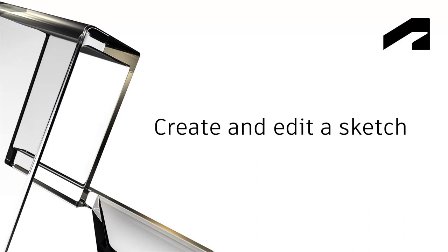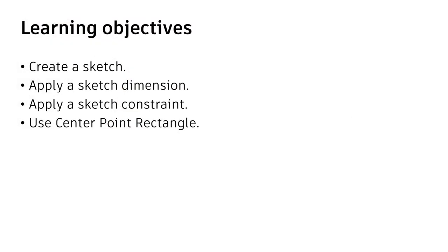In this video, we'll create and edit a sketch. After completing this step, you'll be able to create a sketch, apply sketch dimension, apply a sketch constraint, and use a center point rectangle.